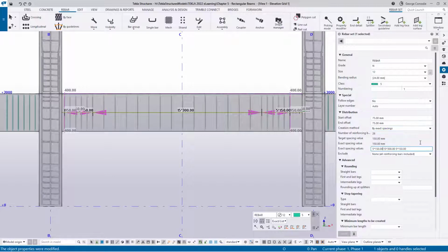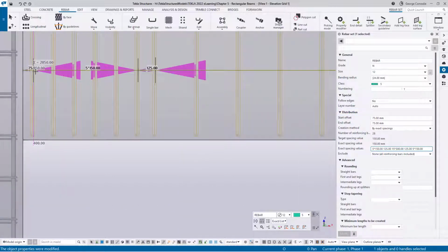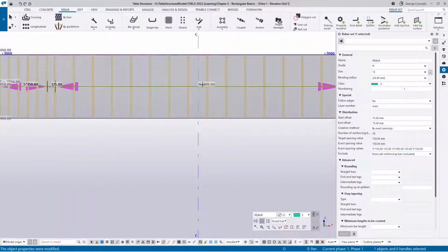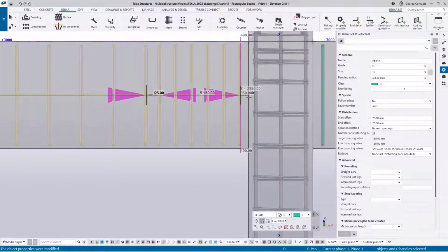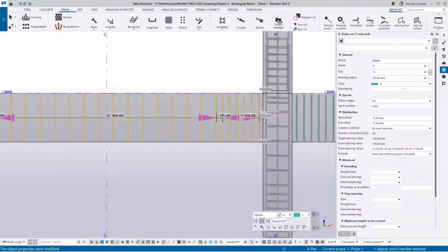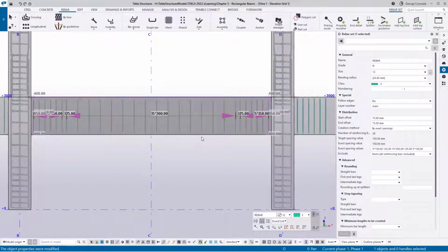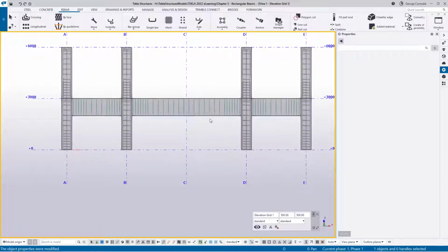So what we'll do is force an odd end and last spacing by putting in a space there and saying 125 there, and click there and say space 125 there. And once we enter, we get a perfect spacing. We've got 75 cover here. We've got 5 at 150. We've got an odd spacing of 125. Then we've got a perfect 15 at 300. We've got an odd 125 again, similar to the other side, 5 at 150, and then this side we've got the perfect 75 millimeters again. So 100% set out linkages just like that by using exact spacings. And the result of this is it will go down nicely in your drawings. When you do your drawings, you don't have a decimal value as a spacing.